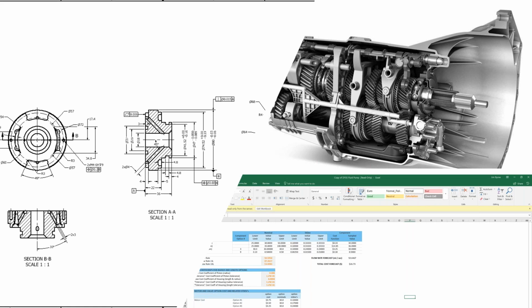A 1D tolerance stack-up means that the distance being analyzed and all dimensions that contribute to the distance variation are acting in the same linear direction. Linear variation of the surface on either side of the stack-up direction is considered. Angular variation of the surfaces relative to each other is not. And sometimes the effects of the angular variation are overlooked, and the analysis is considered to be 1D.